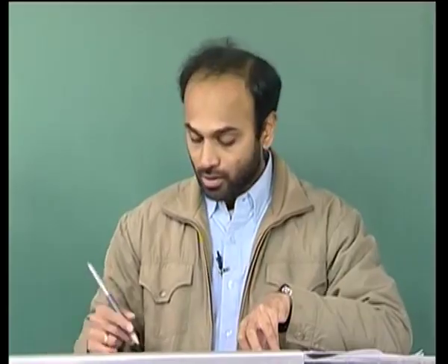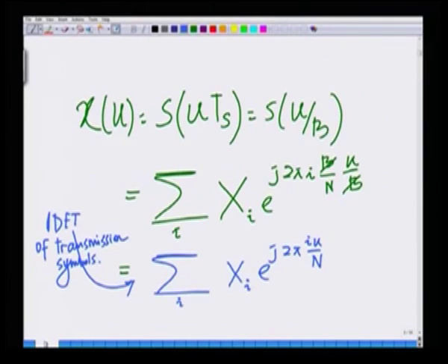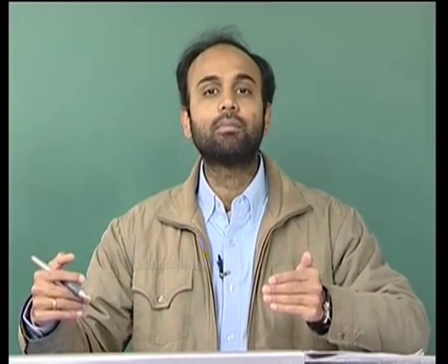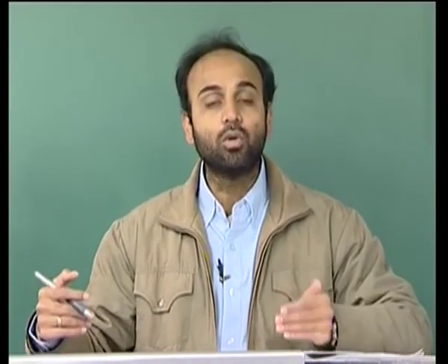All right. So, in practice what it means essentially is that from the structure given here, I can take my transmission signal symbols to be transmitted, that is x0, x1 up to X of n minus 1, and compute a simple IDFT of these symbols, or the IFFT of these symbols, to generate the transmit signal, and there is no need to use the n modulators for the n subcarriers, which, as we saw, greatly increases the complexity of this system.